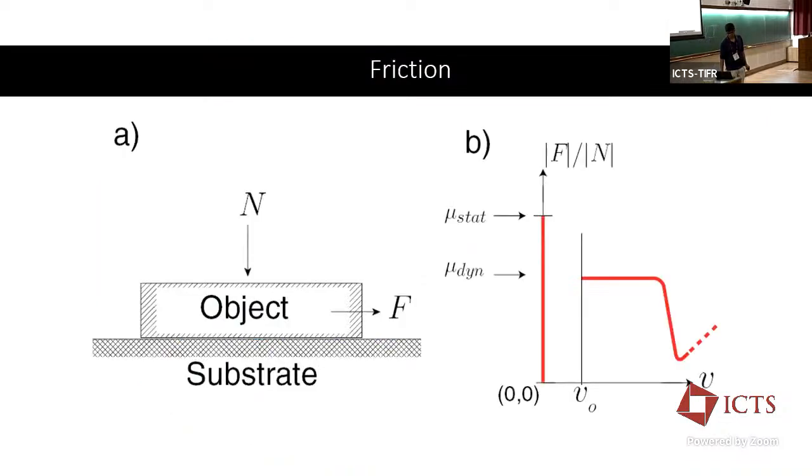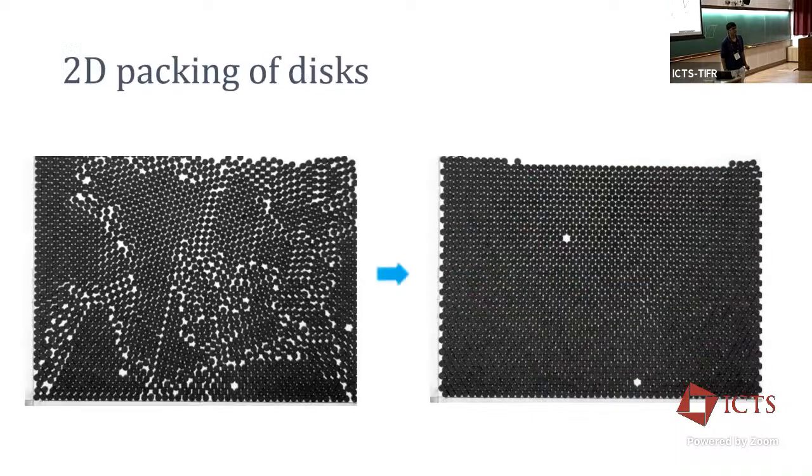You mentioned vibration also, right? So under vibration, if you don't apply shear, if you do the same thing under vibration, will the phenomena be the same? No, under vibration, you will never be able to get one crystal. What will happen is that your defects will constantly start to move. Because you're giving enough energy to the system, if that energy is enough to anneal something, it is enough to also create a defect somewhere else.